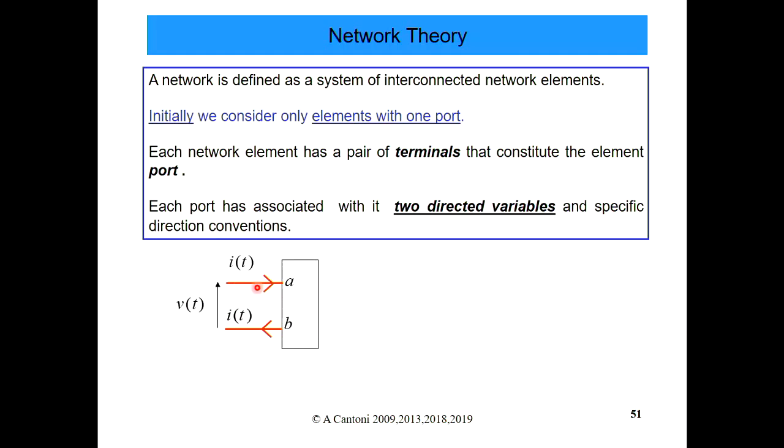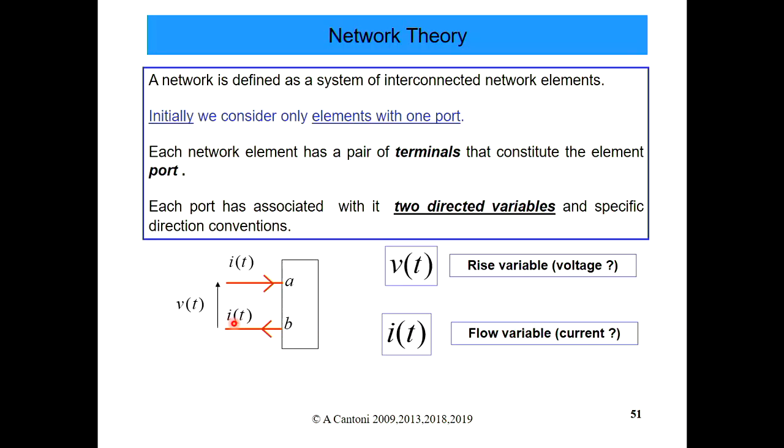And we have the flow variable, which is the current. The big thing is that current in equals current out. Well, the magnitude of the current going in equals the magnitude going out. So it's just two variables associated with an element. That's an important concept, and it's related to the fact that it's dimensionless. If you put current in, then the same current comes out. If the element was too big, that wouldn't be possible, because the speed of light wouldn't allow it to happen. There'd be some delay.